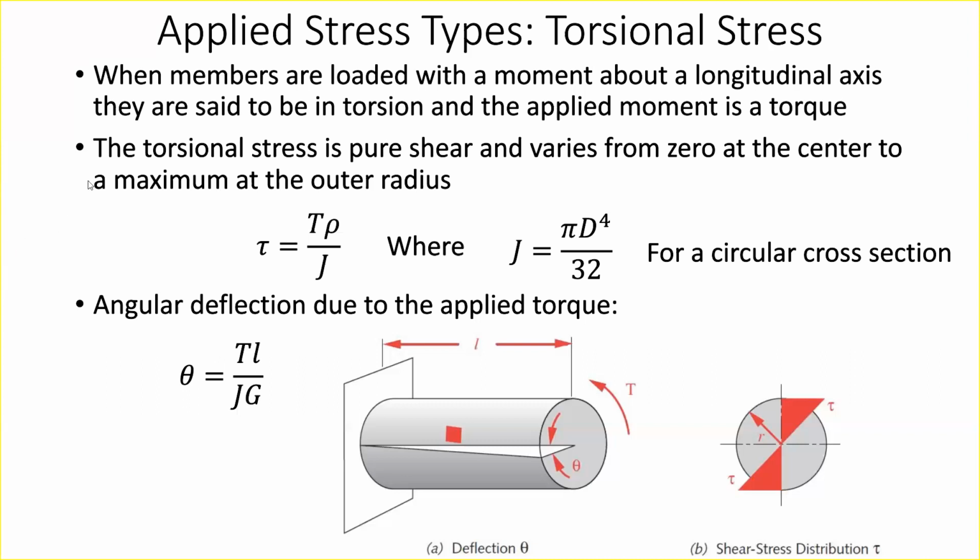So again, there's just standard formulas for this, but what you should recognize about shear load cases is that the shear load is typically highest at these edges, or the further in radius you go out of the part, the higher your shear load. So if you remember back to the normal bending load case, it's somewhat similar where you get these peak stresses on the outside of the part. So it's no different here. The peak stresses are on the outside of the part, and typically you identify those stresses first, and you check your part strength based on those peak stresses on the outside.